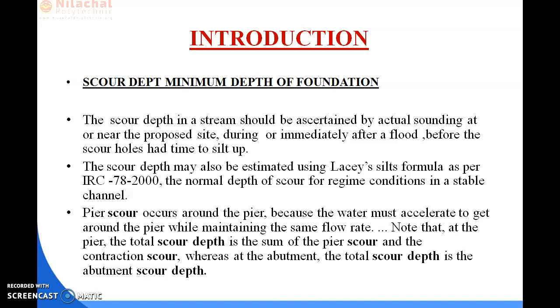So first, before we enter the chapter, we discuss what is foundation. Okay. So a foundation is the part constructed under the pier or abutment and over the underlying soil or rock. And the loads transmitted by the foundation to the underlying soil must not cause soil shear failure or damaging settlement of the superstructure. Okay.